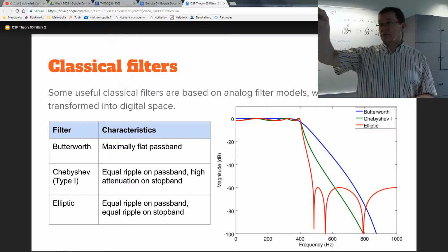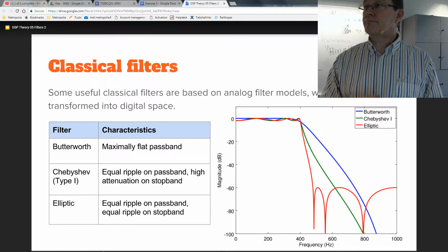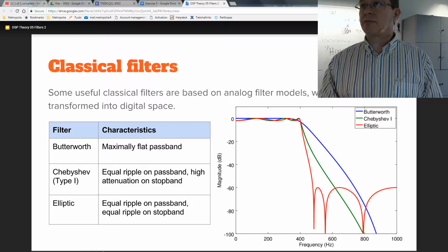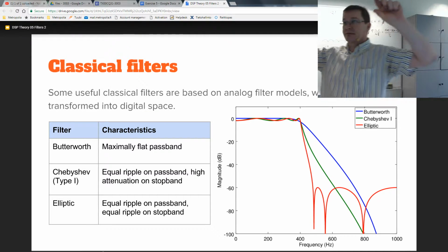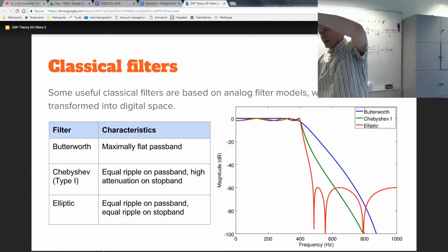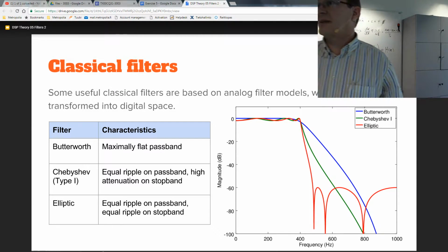Okay, and yeah, that's the history. So what does the equal mean? Equal ripple means a uniform ripple within, say, plus or minus 2 dB on passband, and then you know the stopband attenuation level. In that case, -60. Yeah, peaks at the same level.